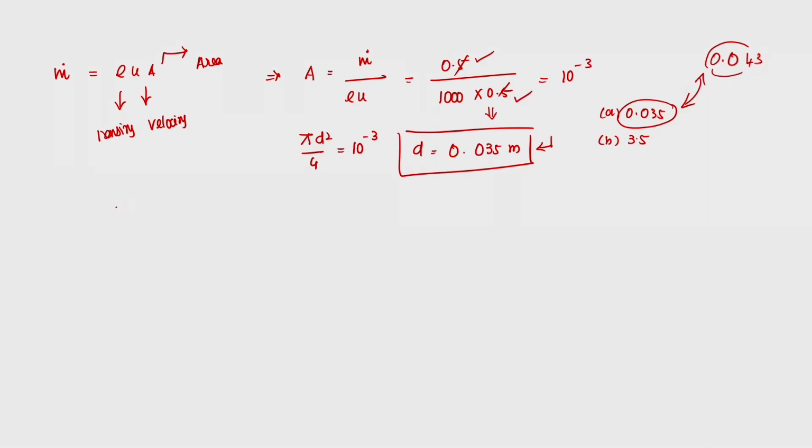The next thing we are supposed to calculate, because it was asked, is the length of the holding tube. The length of the holding tube is Ft into U max, the maximum velocity. Ft is the residence time, the time required in the holding tube, which is a process value.